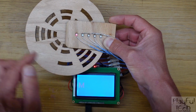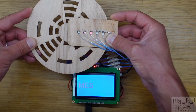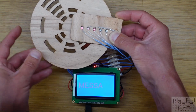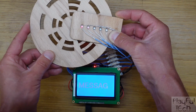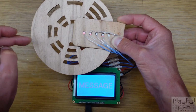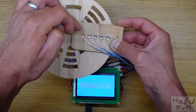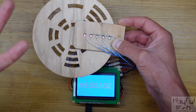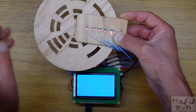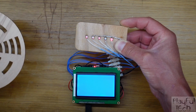So we see the letter M comes up to start with, then E, and hopefully you'll be able to see the message appearing. I'm afraid I do literally mean the message appearing. So these sectors encoded the letters M, E, S, S, A, G, E, and then this final sector here, which has got all 5 segments with holes in, that's kind of like a reset which I've put into the code. So that will blank the screen, and that's equivalent to if the disk wasn't there at all.